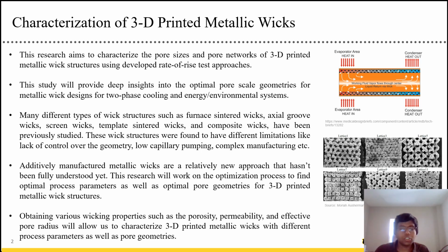My main role is to characterize different 3D printed metallic wicks and sometimes even furnace sintered copper wicks using something called a rate of rise test. As you can see in the top right image, you have the wick structure and there's a fluid inside it. When it's in contact with the hot area, the fluid evaporates and expands over to the other sides. Once it's in the colder region, it condenses and forms the fluid, and the wicking capability of the wick structure allows it to move from the cold area back to the hot area.